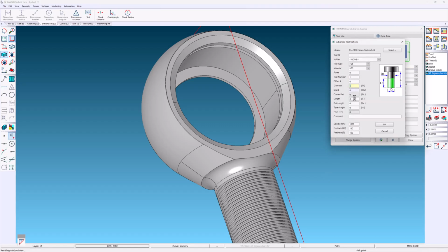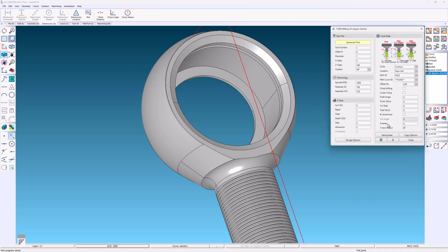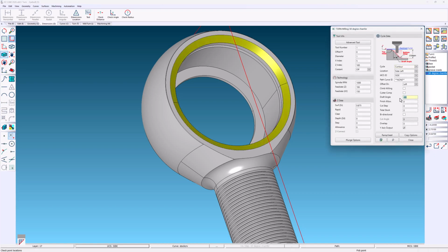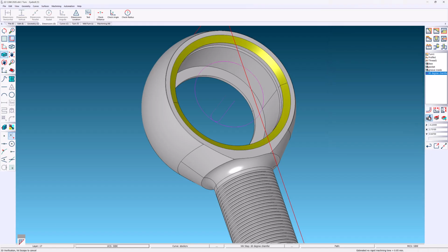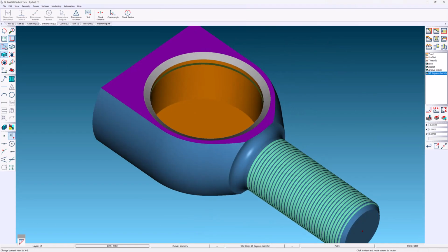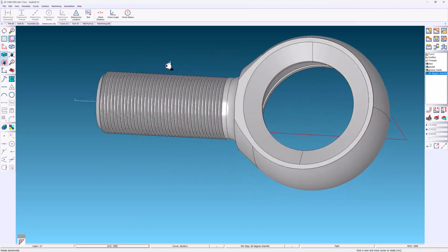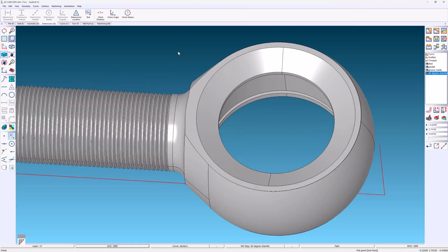From here, we're going to follow the same steps as in previous operations. Based on our surface selection, EasyCam automatically adds the draft angle. Machining the flip side requires adding a coordinate system that is in alignment with the next set of milling operations.